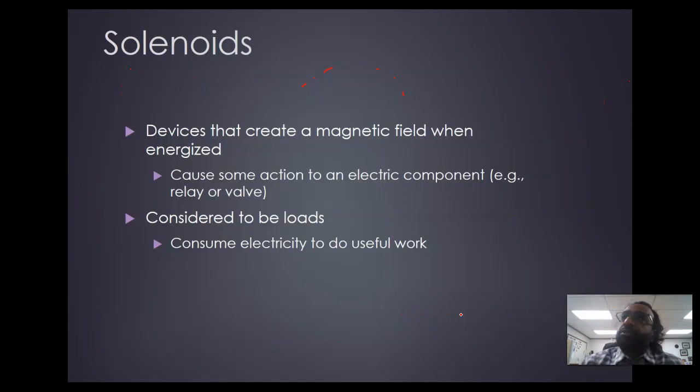Solenoid. What are solenoids? Okay, I'm gonna need you to remember what solenoids are. Solenoids are motorized switches, meaning there's a coil, and when this coil is energized, it pulls a pin up or down. So in the morning when you turn on your car, before you turn on the ignition, if you put the car in the on position, you're gonna hear a lot of solenoids opening. You're gonna hear a lot of ticking. The air pump will click and open the air inflow. You also hear the gas pump. You also hear a lot of clicks. So solenoids basically open and close using a magnetic field.